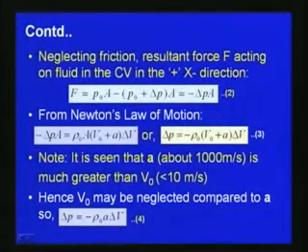So, we can see that delta P is equal to minus rho 0 into (V0 plus A into delta V). If we consider V0 much smaller compared to the water hammer velocity, which is about 1000 meter per second, we can neglect V0 here, so that we can write delta P is equal to minus rho 0 into A into delta V, equation number 4. We have neglected V0 since A is much higher compared to V0.